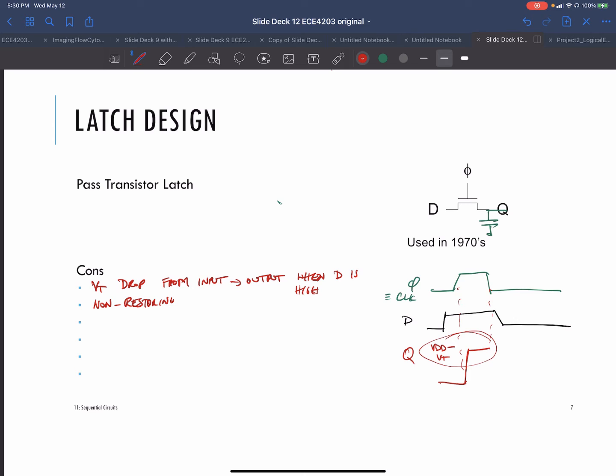And when the clock goes down, there is charge here, this channel charge, negative charge. Some of it will go back to the input, but some of it will get dumped here as you turn this device off. So actually you get a further reduction, a lower-going pedestal here, because of the so-called charge feedthrough. We haven't really talked about this, but it happens in analog circuits quite a bit, and here too.